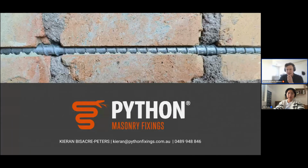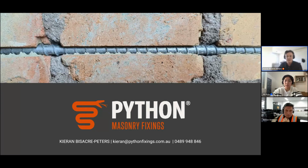Yeah, great question. Both approaches have been tested, and there are good research papers looking at timber studs and timber strongbacks taking the full mass of the masonry wall and doing all the work, and there's also a composite approach that you can use if you need to sharpen the pencil a little bit in the design. I'd be more than happy to share those research papers with you, Alex, after this. And where there's no specific engineering design, spacings will be adopted at AS3700 spacings.